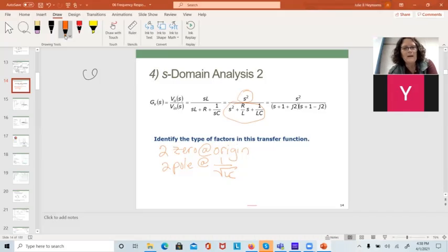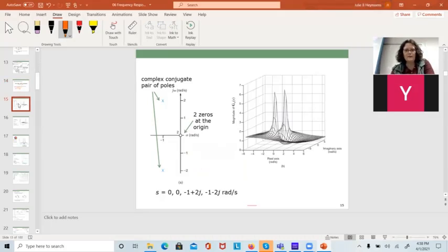Okay. And we plot this. We use Mathematica, believe it or not. I didn't do this. To plot these poles and zeros. Notice this is like a good controls engineer. The right half of the plane doesn't exist. It's not even drawn as part of the axis because it's unstable. I have two zeros at the origin. These make marginal, wait, does it? No, it makes it unstable.